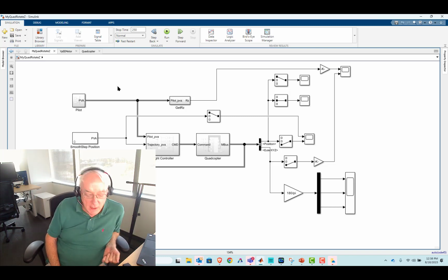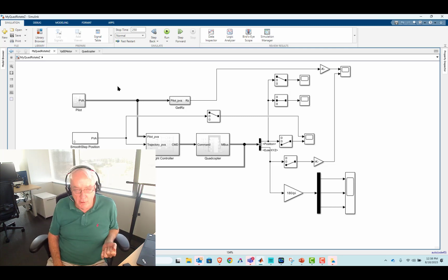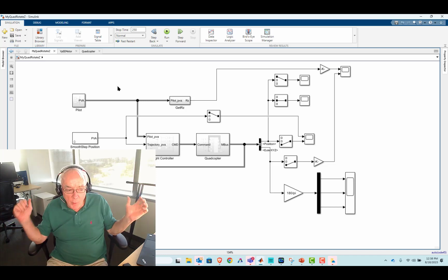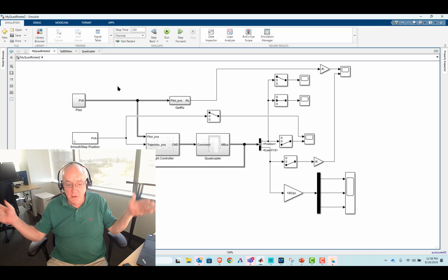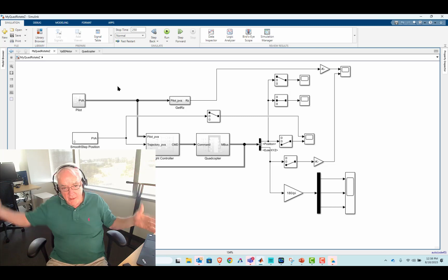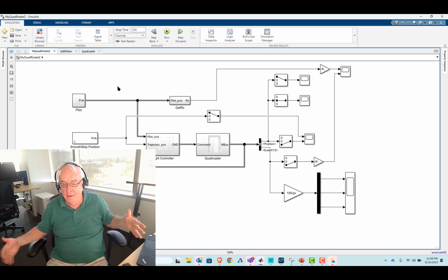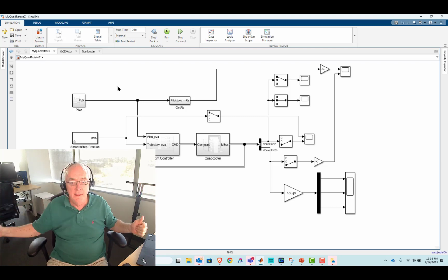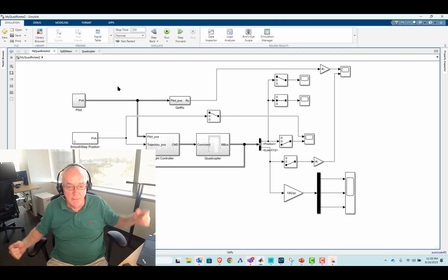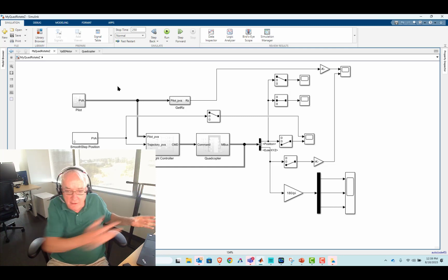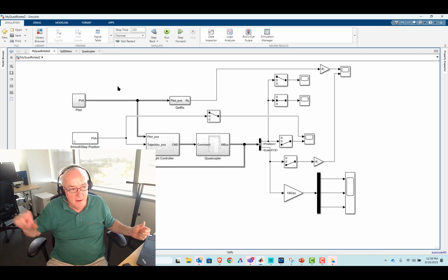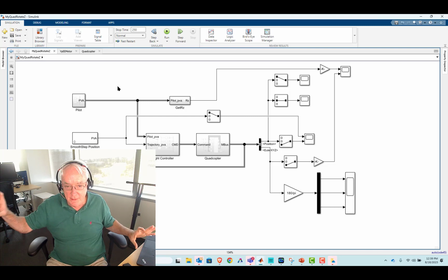thrust control, right? And thrust control, of course, works great for pitch and roll. For R cross F, F is thrust, and more precisely, the incremental thrust. And we talked about that to get the torque, let's say, that will rotate it about its y-axis. I think that's what we call roll. It means give a little bit of positive thrust on the X end, or I'll say the positive end of the X beam, and a little bit of negative thrust on the negative end of the X beam. I might even have the signs wrong on that, but it's that idea that the incremental thrust is equal in magnitude but opposite in direction.